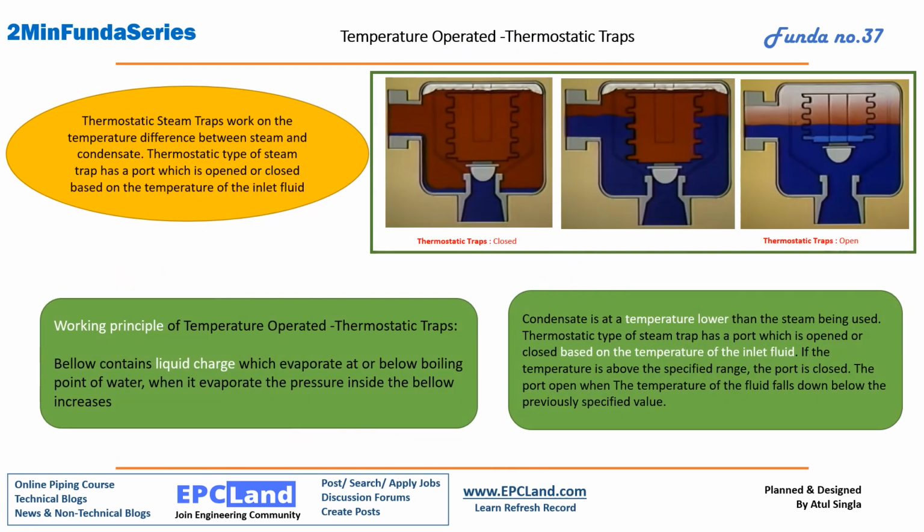Thermostatic traps, as the name suggests, are temperature operated and work on the principle of temperature difference between steam and condensate. As you know, condensate is always at a lower temperature compared to steam, and that is the basic principle. Based on the temperature of the inlet fluid, whether steam or condensate is entering, this trap works. To understand the working principle, we need to understand that the bellow inside this trap is charged with a liquid which evaporates at or below the boiling point of water. This is the basic principle of working here.